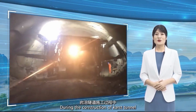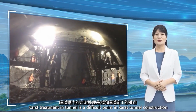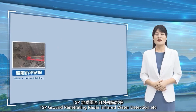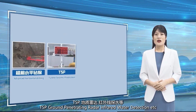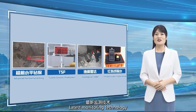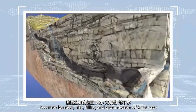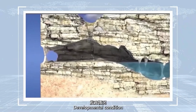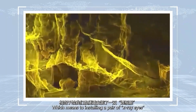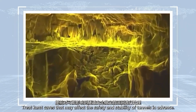During the construction of karst tunnels, karst in the tunnel cavern is a difficult part. With the help of advanced horizontal drilling, TSP, ground-penetrating radar, infrared water detection, and other monitoring technologies, we can identify the location, size, filling, and groundwater developmental condition of the karst cave, which means installing a pair of X-ray eyes in tunnels, so that what may affect the safety and stability of the tunnel can be dealt with in advance.